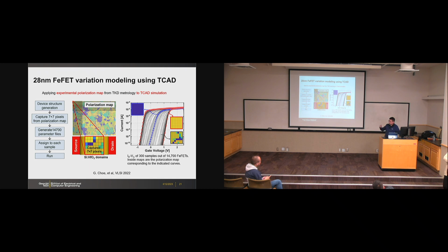The reason we want the intermediate state is here, where we have the mini loop. If you only need the 1 and 0, you always operate on the largest loop. That's no problem. But if you want to go to the intermediate step, my suggestion is do not switch between those two middle states, let's say you have 4 states. You always go to the ground state and then go to the middle states to avoid the history effect. This is our suggestion. Of course, if you only need 2 states, the very up and very down state, then that's fine, no problem.